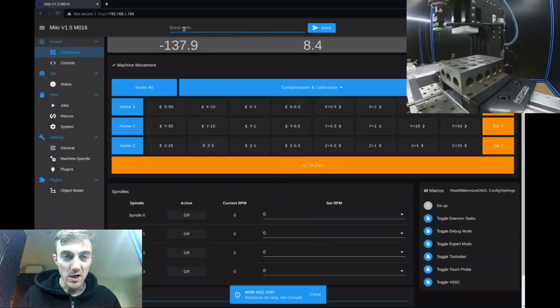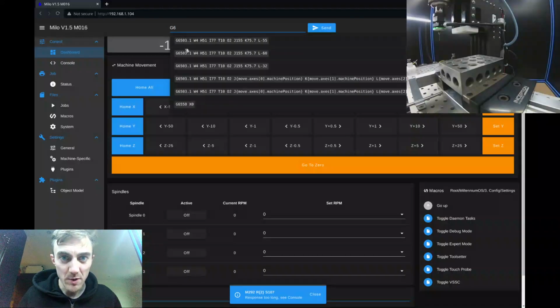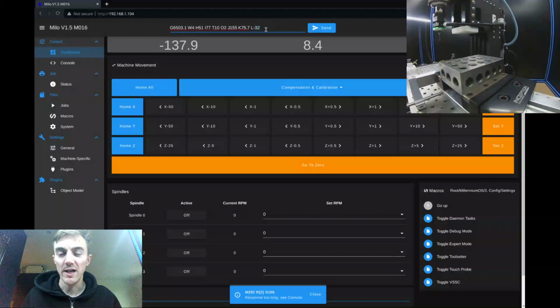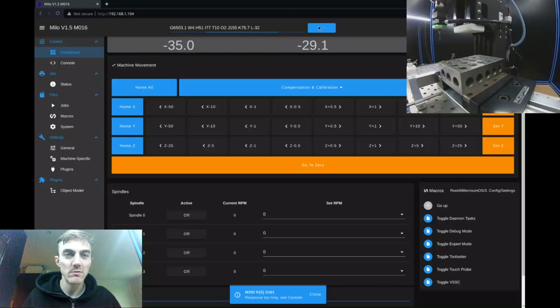Now I have another command which is the same command here, but designed to be used with the touch probe. It's exactly the same, except that the length value is different, because the installed length of the touch probe and the datum tool are different. In practice, when you use this macro, if you're not calling this particular macro directly, you will be jogging the tool around to make it work. So you won't actually need to enter heights and that sort of thing.